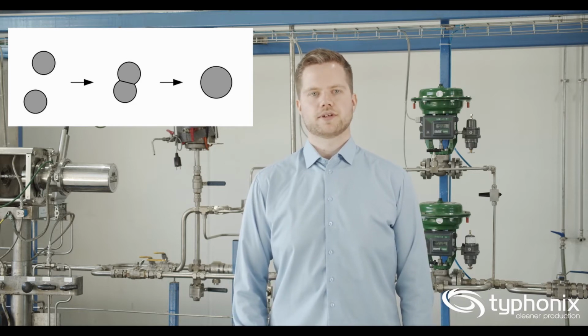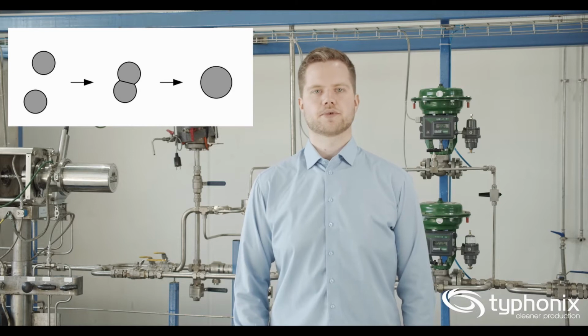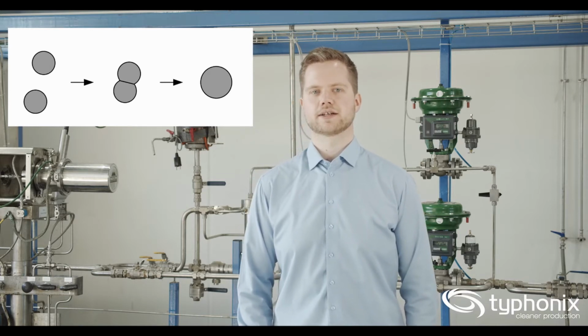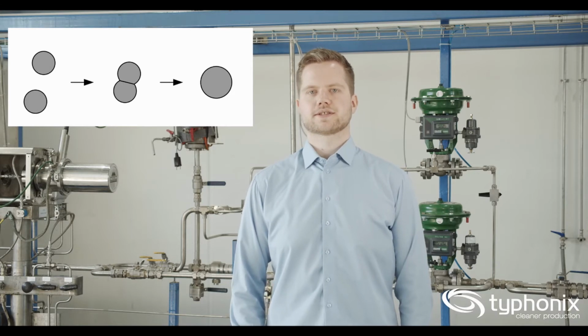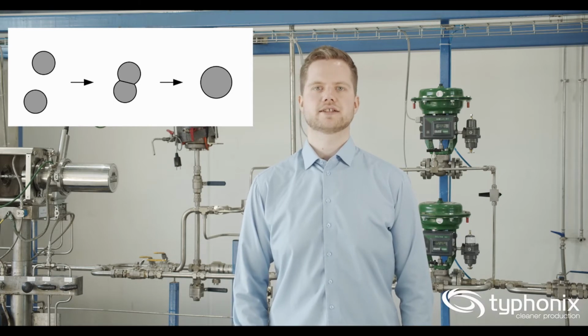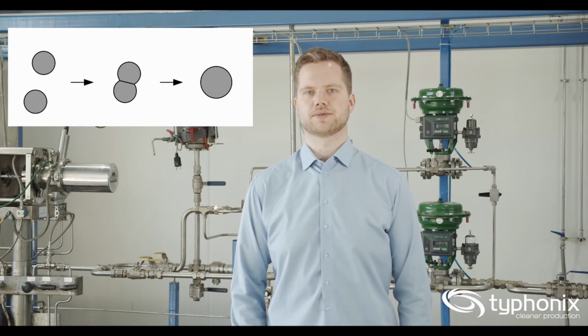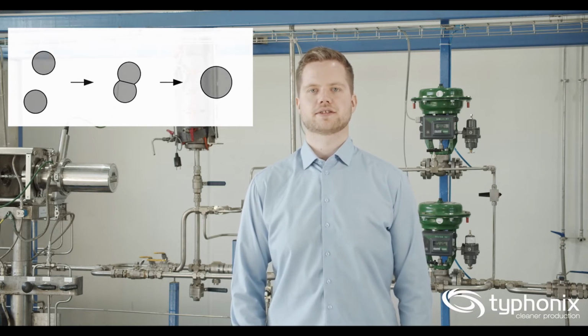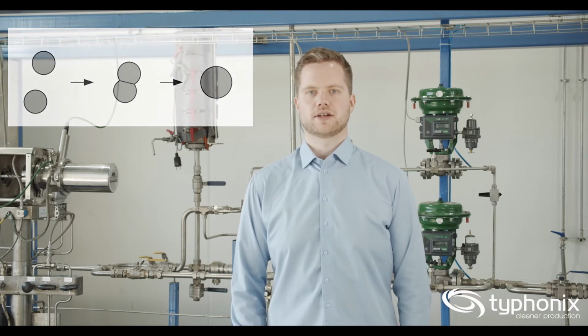For the collision frequency, the number and size of droplets also plays a large role, where a higher number and a larger size increase the likelihood of them colliding. Regarding the coalescence probability, 2 droplets have collided, and you want to drain the film between them. Now, the drainage time and the time the droplets are next to each other is what governs the coalescence probability.